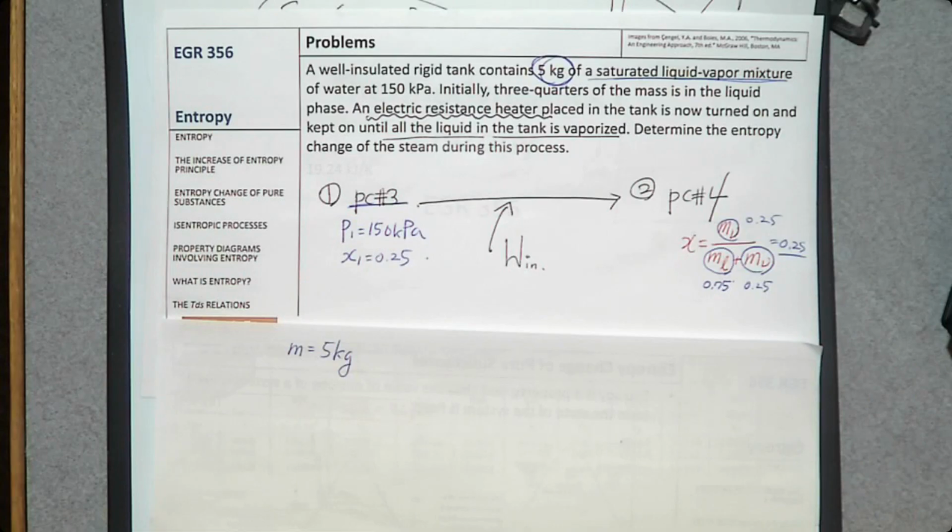What about the final state? What do we know? Oh, that is saturated vapor. What else? That's all we know. So can you analyze the final state? Can you find H? Can you find U, V, S? You can't, because you only know it is phase change process number 4. So you need another piece of information. So what is it?